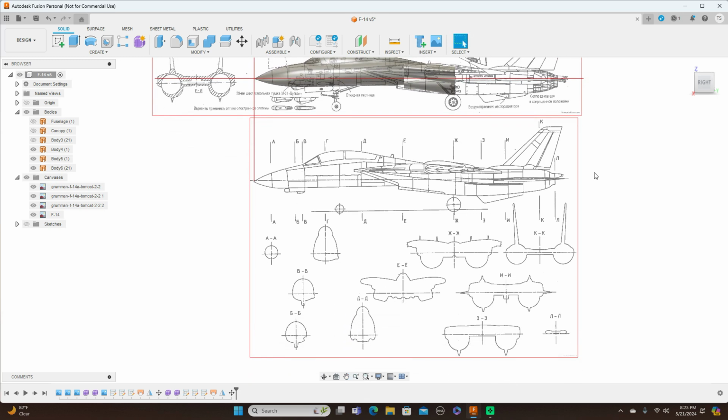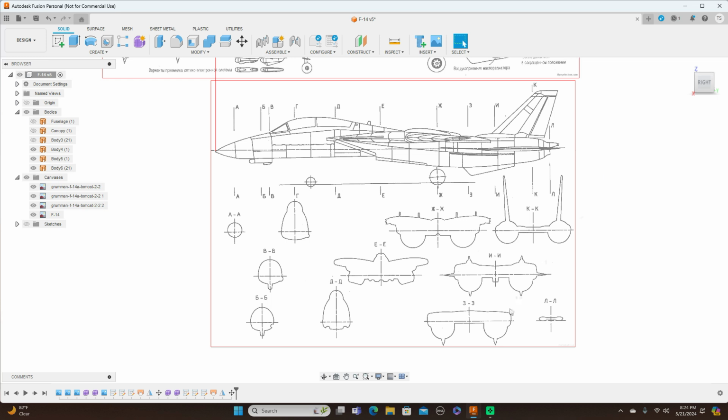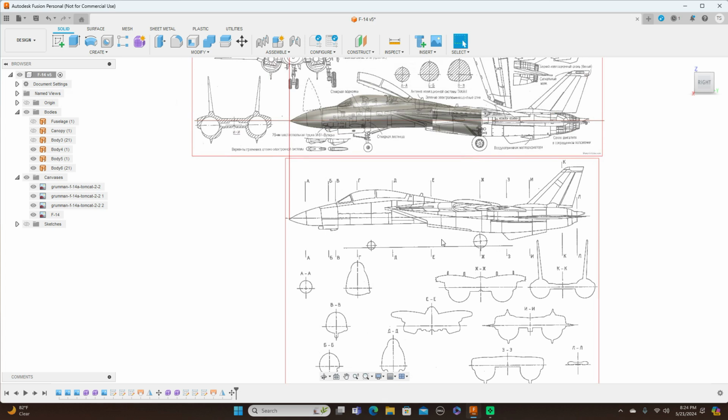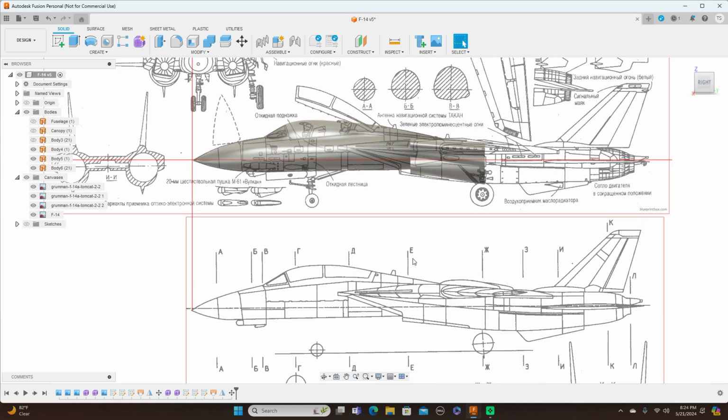And the rest of this plane, the back of it, you have the formers here. You'll just have to split, like I split these here with all this under here. All this other stuff like this, you're not going to model this on here. None of this. So you get your lofts to look right, and as soon as your lofts look right, then you'll go back in and put all this other extra detail in, the vertical fins and other little things. But yeah, so just want to show you guys some more modeling techniques.